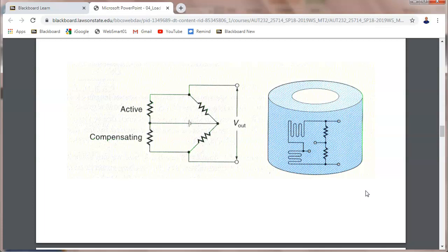We bought a scale. They bought an electric scale. The problem we have with big truck scales is that it gets debris on it all the time. It was on what we call the line scales. And those things come with auto zero, which means if there's nothing on the scale and there's no motion on the scale, these guys constantly zero themselves out. And then when you pull something on there, you're not getting the weight of the weight bridge, you're getting the weight of the vehicle, right? You understand? And they would weigh twice.